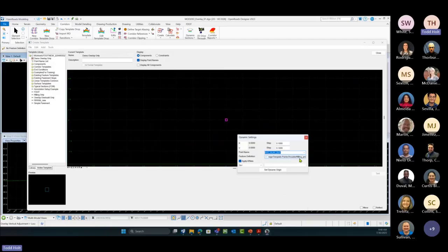That's going to set our feature definition based on that point name. And then we're going to use the prefixes of our HS, horizontal and slope. That's going to give us a distance from our origin. We're going to set this to 10, 2. So we're going to be 10 feet away from our origin at a 2% slope. We'll come back to this later.